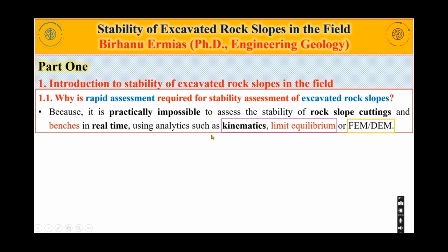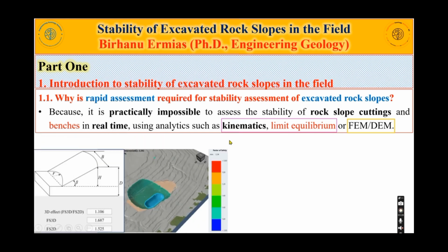because these analytical methods take time, require input, and are analysis techniques that we carry out in the office, not in the field. Rapid assessment method is required for stability assessment of excavated slopes in the field, while these are methods that we apply in the office and require some software and inputs.